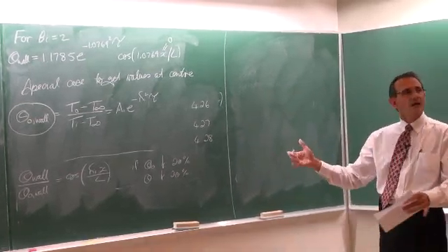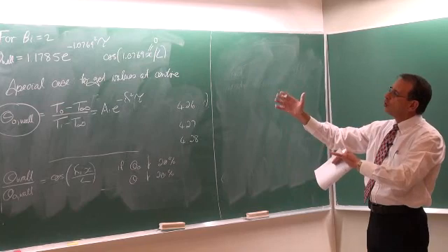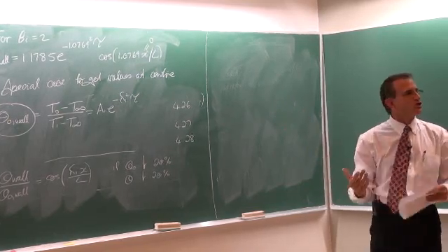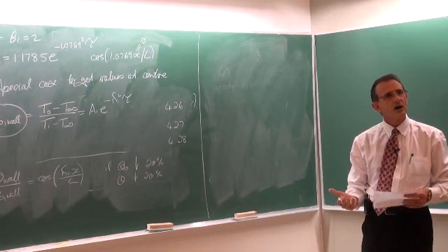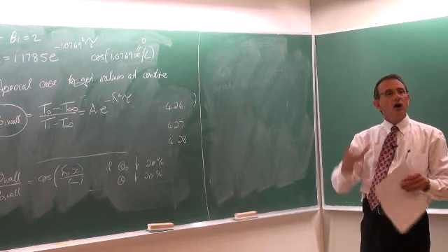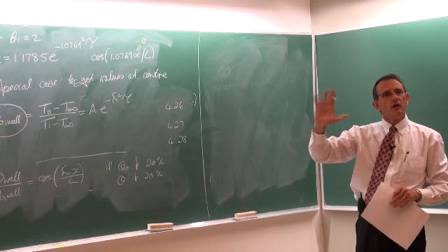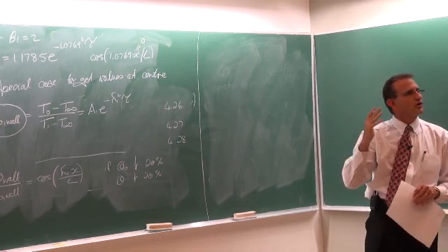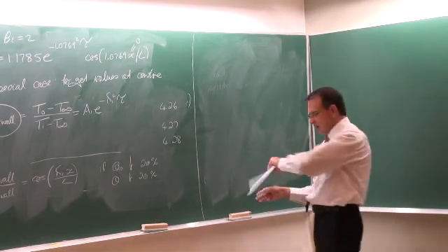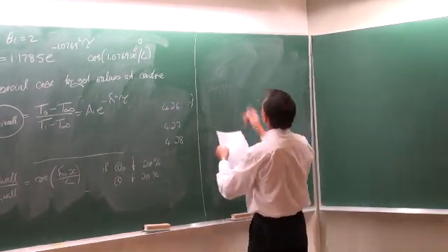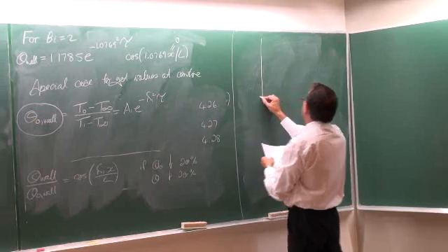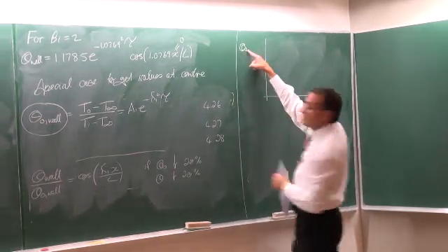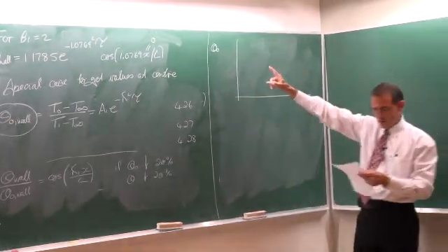And this fact can then be used to also describe all the results in a graphical format, which is called the Heisler charts. The Heisler charts. And there are 3 of them for every one of the geometries. So in total there are 9 charts for the 3 geometries. Okay. And the charts look like this. The first one gives us theta 0. Take note, theta 0.